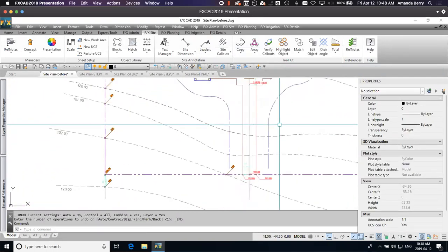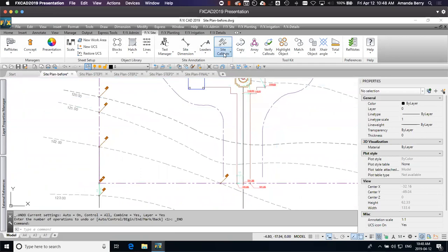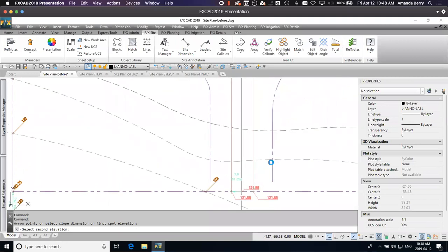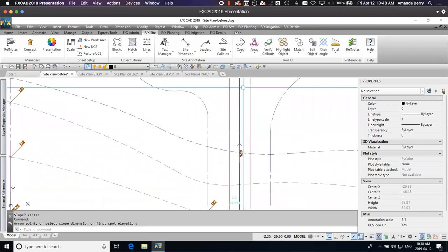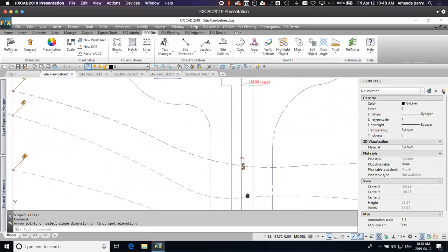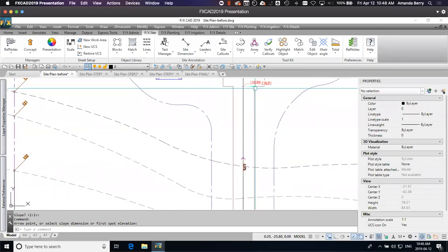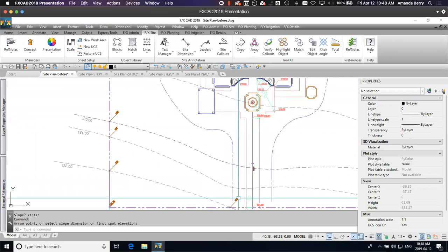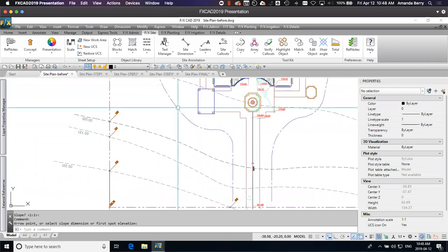And then it's basically kind of what I was doing before. I can grab that slope call out, grab this spot, and figure out that that's 6.9 and start filling in this crown through here. And I probably want spots here, here, here, and here. And basically what that's going to bring me to is now being able to figure out how to grade my